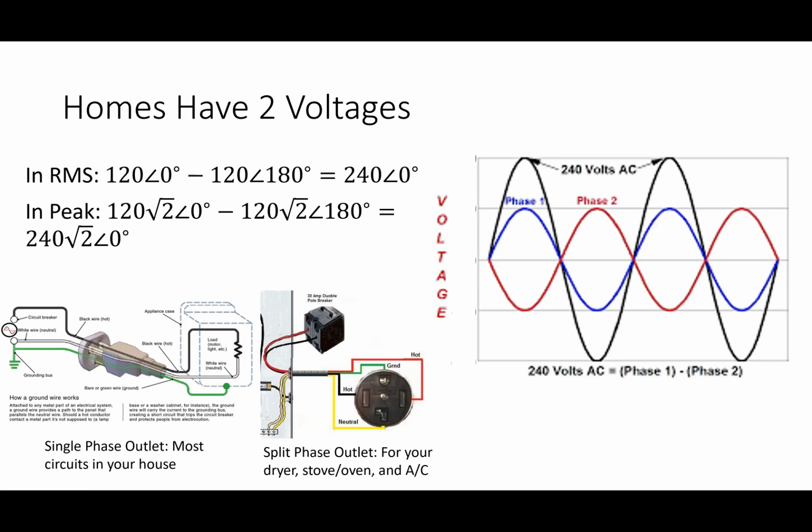All right. If there's ever current going through the ground, oftentimes, like in your bathroom or your kitchen, you have those GFI circuits, right? What's GFI? Yeah, ground fault interrupt. Basically, it measures the current going through that ground wire. And it says, hey, if there's any current going through that ground wire, there shouldn't be because it's not part of the circuit. It makes the assumption that if anything's going through there, it's going through your body, which is connected to the ground. And so it interrupts.